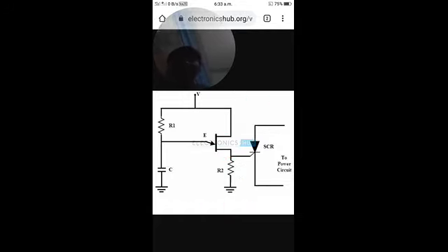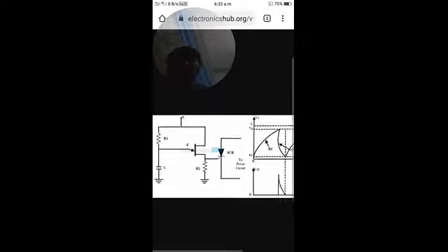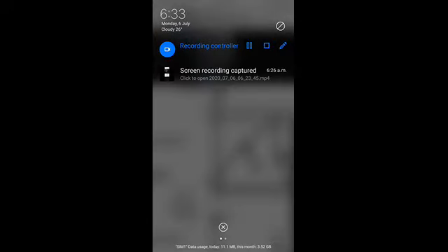Now the capacitor is gradually charging when the supply is given. We have a voltage VP on the output side and the emitter is at 0, so the UJT is in the off position, but the capacitor is charging gradually from 0. The voltage of the capacitor is the emitter voltage, which is increasing gradually from 0. In the process it will reach a voltage equal to VP.